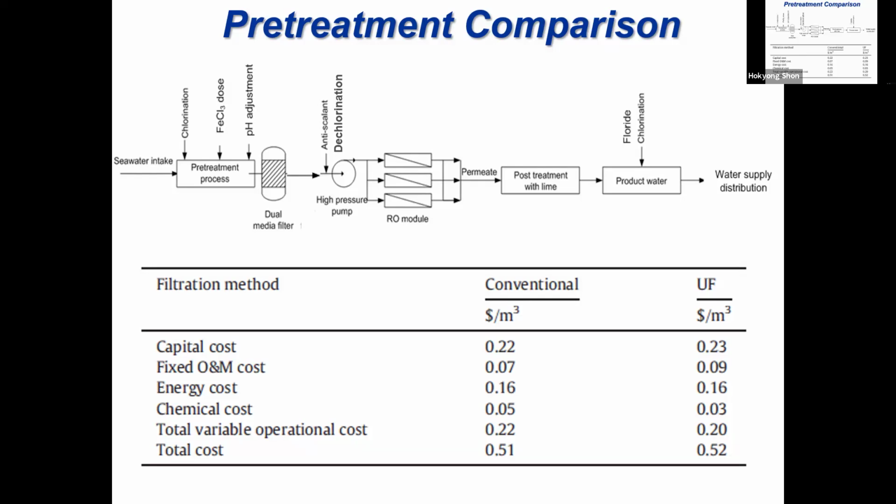You're packing the sand. There are still a lot of small particles that could pass through your media filter. But with the ultrafiltration membrane, you can remove most of the particles so that you will have a better quality of treatment. Previously, a lot of people utilized pure media filters because they are very cost effective and very easy to operate.